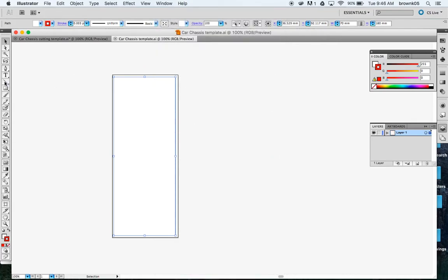To begin, I want you to select the Line Segment tool. You click on that, it then gives you the crosshairs, and anytime you move near a line, you will get a green leader helping you to find where you need to draw. To do our first line, I want you to move your cursor down towards that corner box. You'll notice that a few words appear. You've got intersect, you have camber, and you also have anchor, which is now shown. When you see the word anchor, you can click.